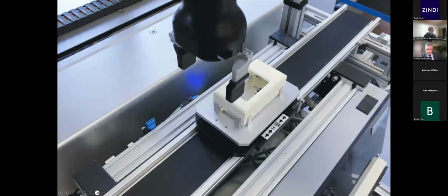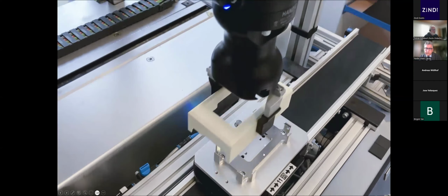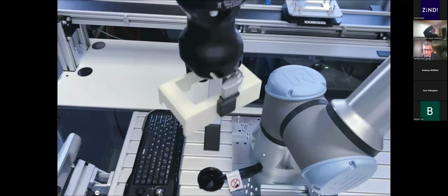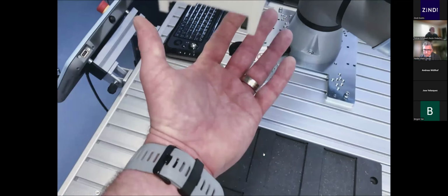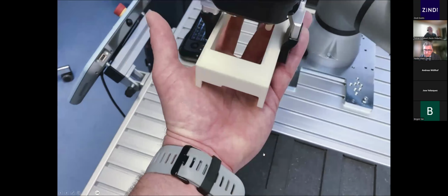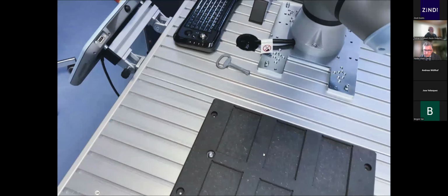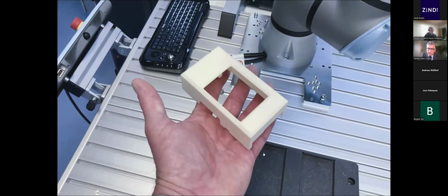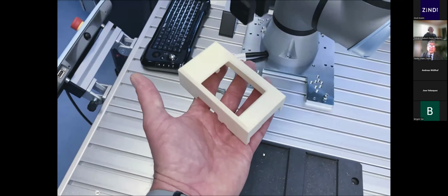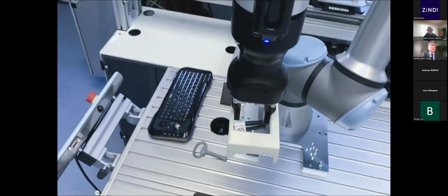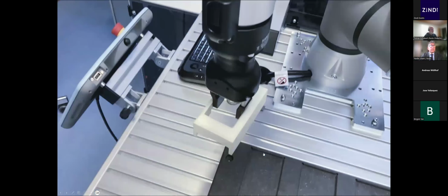Okay, here it's the other way around. He's taking a workpiece and placing it into my hand, but the other way works as well. So the key point is you have a camera system which identifies and localizes your hand and puts the workpiece into your hand. Here it comes. That's the other way around. So of course you need a 3D camera system to guide the robot where to go and then grab or place the workpiece.